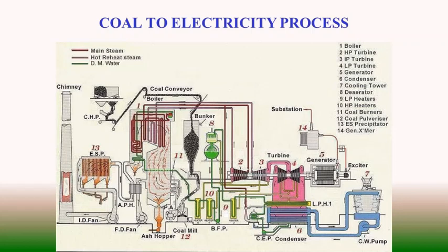So naturally there is quite a significant amount of heat lost with the circulating water system, and this loss of heat can be minimized with the introduction of the regenerative feed water heating system. For that reason, to increase the thermodynamic mean temperature of heat addition, we incorporate regenerative feed water heating as a modification of the Rankine cycle for better energy output and efficiency enhancement.